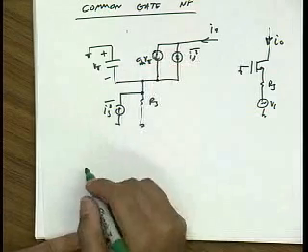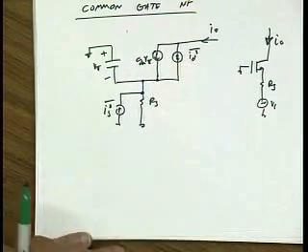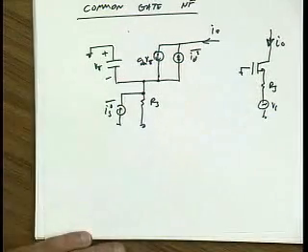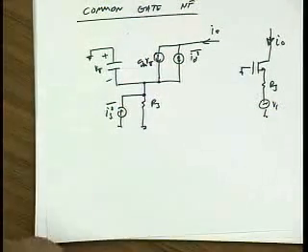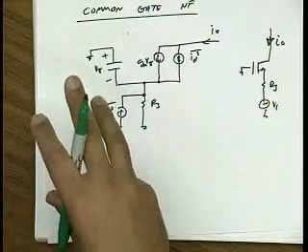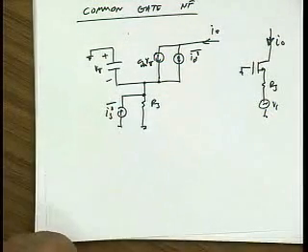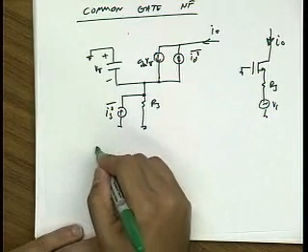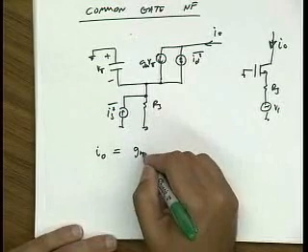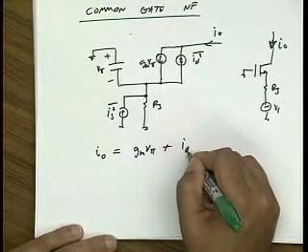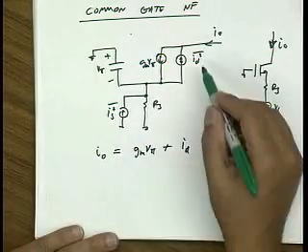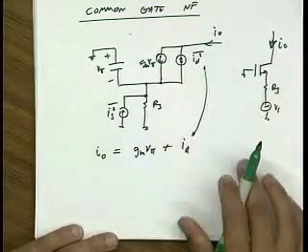All right. So the idea is, in this problem, we're going to work with voltage signals, and then at the end, hopefully we're going to have a sum of independent variables, so that we can find the RMS value by just summing RMS values. So what we're really after is I out, which we notice is the sum of gm V pi and the drain noise. At this point, we're treating this noise as a deterministic signal.